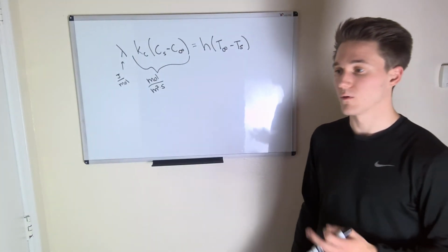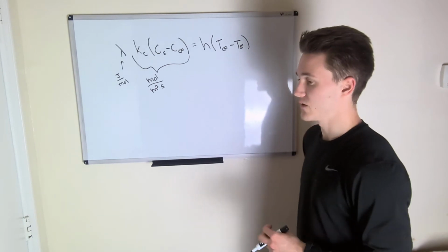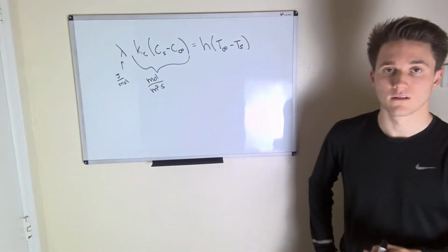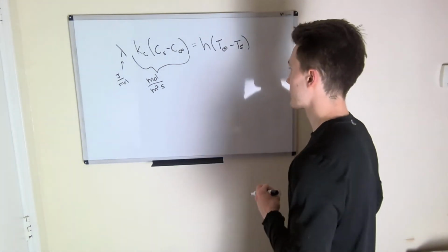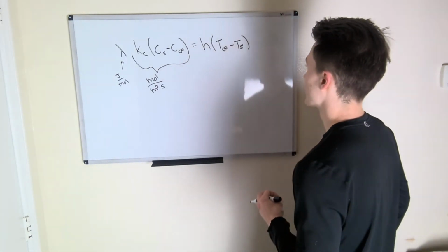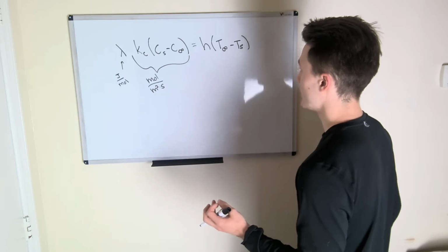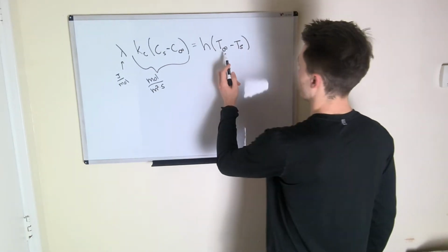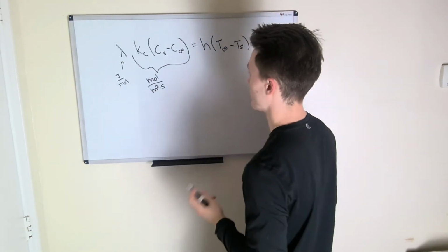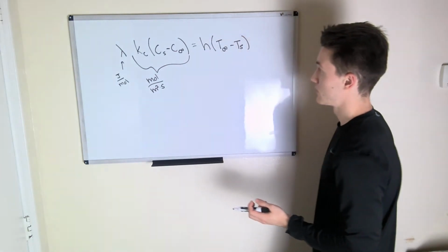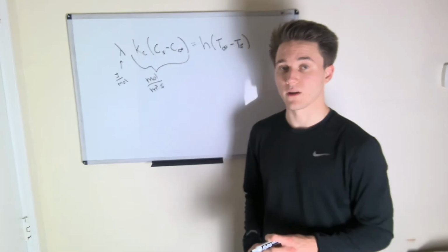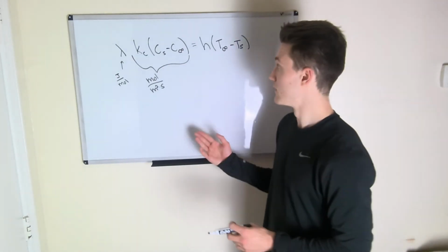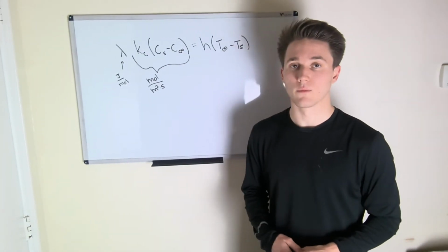And so what this energy balance shows us is that the heat being transferred from the air to the surface of our wet bulb is equal to the thermal energy that is required to evaporate our water vapor from the surface to the air in our wet bulb.